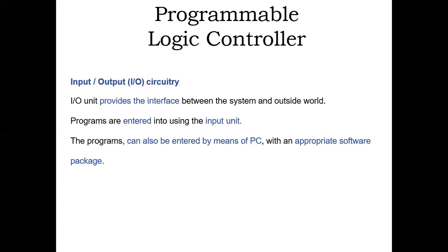As well, if we compare with the microprocessor, a PLC works in 230-volt conditions. A PLC can use many power supplies in real-time applications, but microprocessors use 15 volt or 12 volt, whereas in the PLC we can use 230 volt. The program is also simple, for logic operations like AND, OR, NOT.